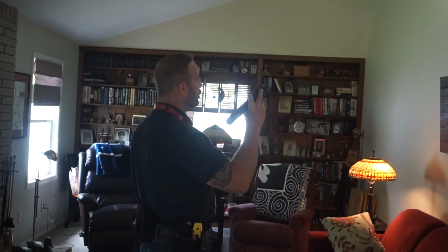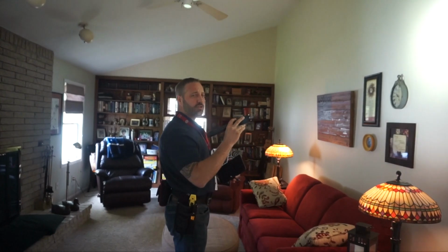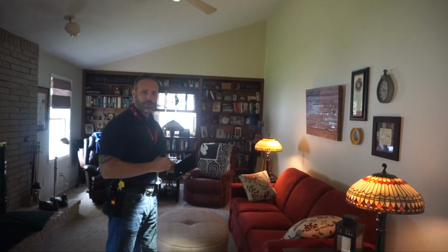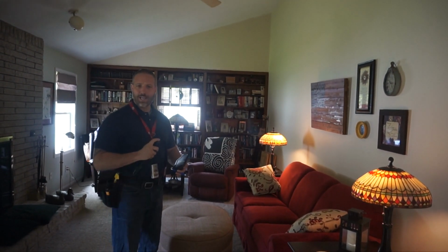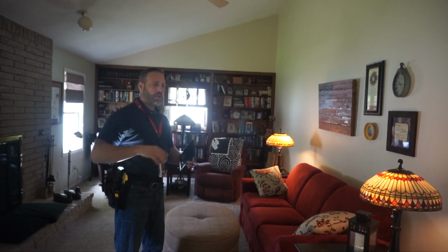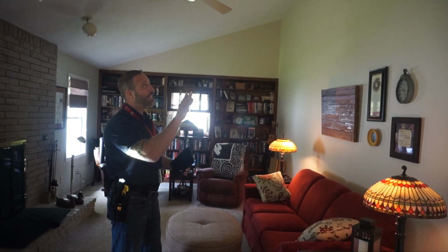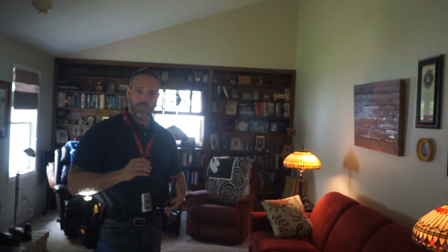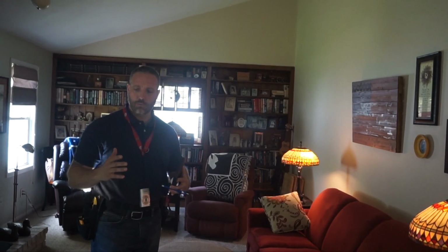So once we get done with the ceiling, we're going to be looking at the walls. And again, we're looking for any water stains. Now sometimes you may have general blemishes, maybe sheetrock damage. Those are considered more cosmetic defects. When it comes to the wall and the ceiling, we're looking for cracks. That's where the structural issue comes in.